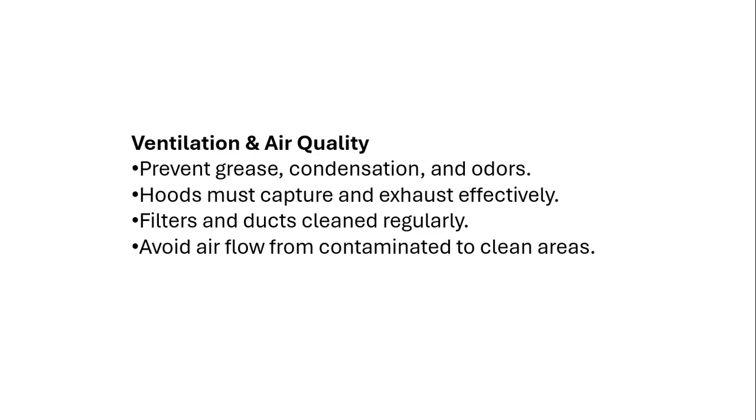Ventilation and air quality. We should be preventing grease, condensation, and odors. The hoods must capture and exhaust effectively. The filters and ducts should be cleaned regularly. And we should be avoiding airflow from contaminated areas into clean areas. That's why it should be pulling all of that out, including fumes from cooking as well, right? If we're cooking on gas, we want to pull all of those fumes from those carbons out from our building as well. But that should eliminate all of those things. If it doesn't, there's not sufficient exhaust going on.